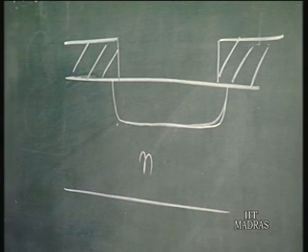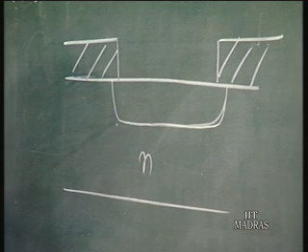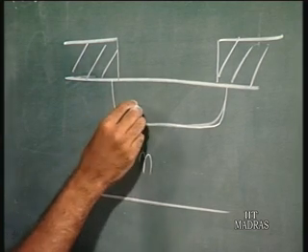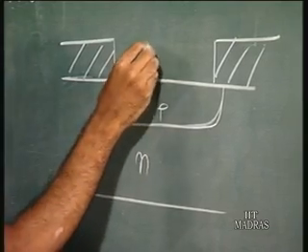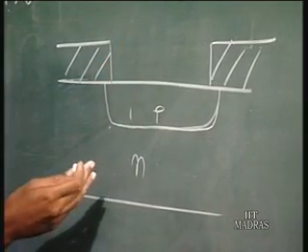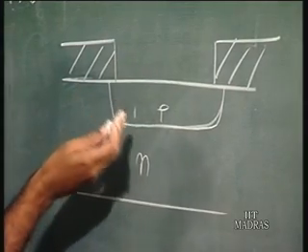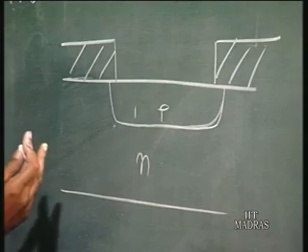All right, you diffuse the base region. Of course, these junction depths show a very big P diffusion, but these are not to scale anyway. So, then what you do is, once you have the P region, you deposit polysilicon all over and oxidize it and etch back. It is something similar to what you have done in the I squared L process, if you recall.